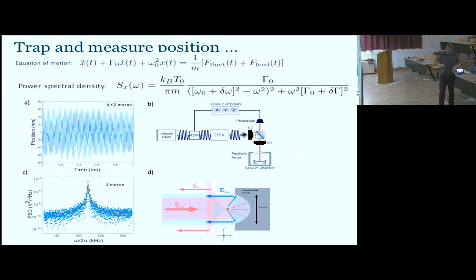Yes, yeah. So as I said, we start at atmosphere, and then we pump down, and the lowest pressure we could reach so far is something like 10⁻⁶, 5 × 10⁻⁶ millibar. Yeah? So you would not call it ultra high vacuum, that is high vacuum maybe.